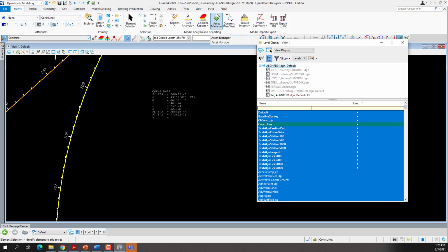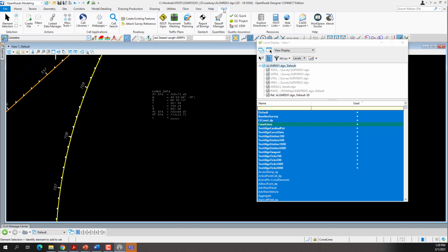What we did on the FDOT tab is go to the FDOT tab, and under Actions, there's a Filters group. Let's click on that split button. That will have different display filters for the different majors according to the different scales. We have one set for only 100-foot majors with 20-foot minors, 500-foot majors with 100-foot minors, and then 1,000 with 200 and 5,000 with 500. So it'll have the correct major and minor, and that's going to display it.